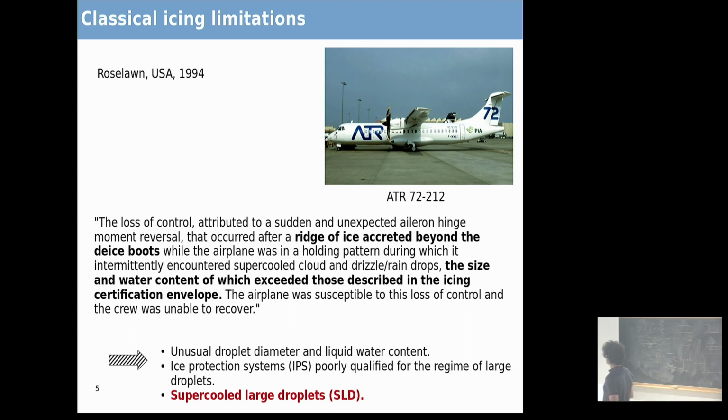And then what they observed was that the size and the water content, the amount of liquid water in the clouds, really exceeded those described in the icing certification envelope. That's why both the FAA, which is the American federal organization for aviation, and EASA, the same thing in Europe, decided to modify certification rules and to run a project dedicated to SLD.